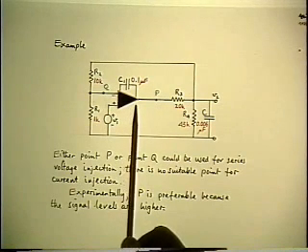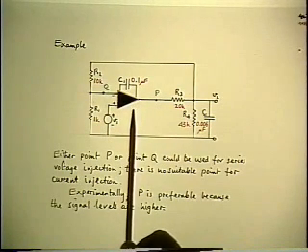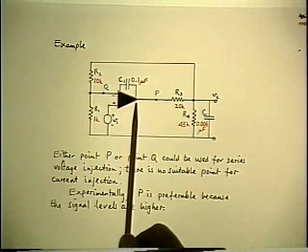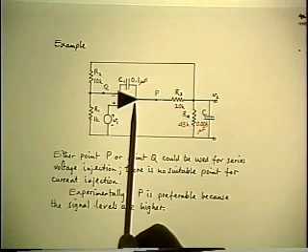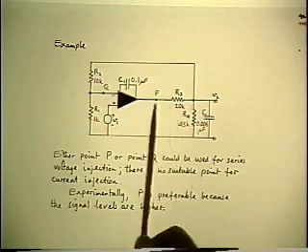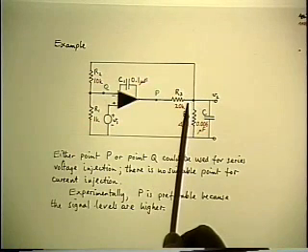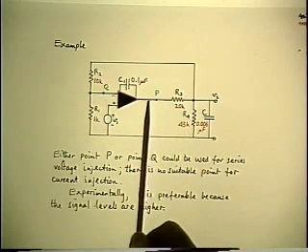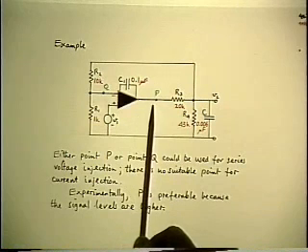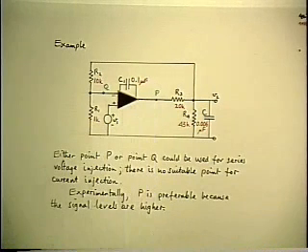I don't remember exactly what it is. It's a few hundred ohms. But anyway, it means that the output of the op amp is pretty close to an ideal voltage source, at least compared to what it's driving into, which is at least 20K. So it's not ideal, but it looks as though it'll be pretty close to ideal in order to do series voltage injection.